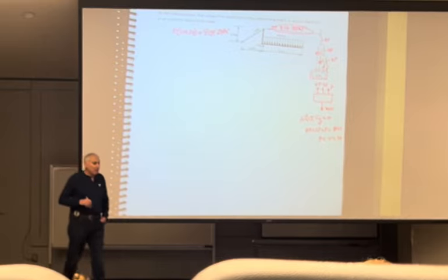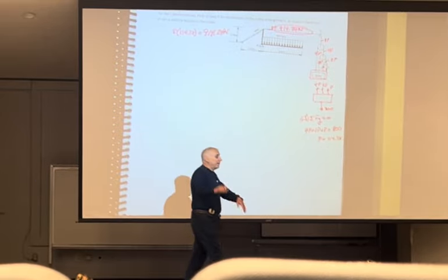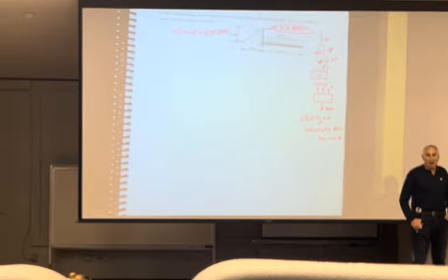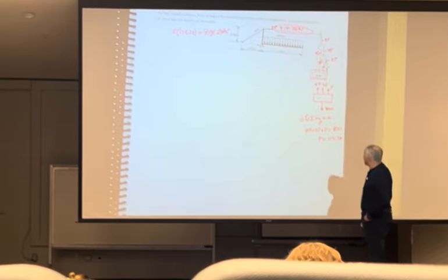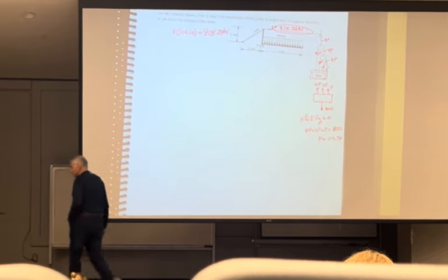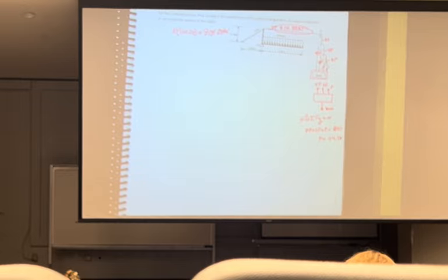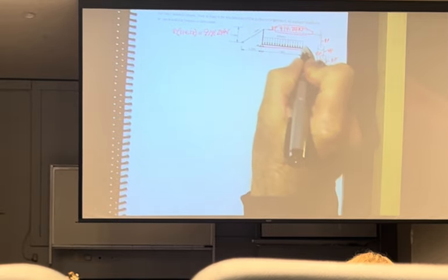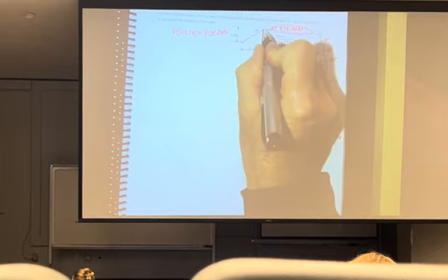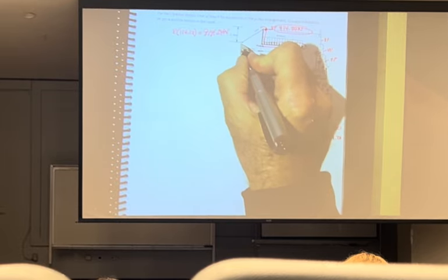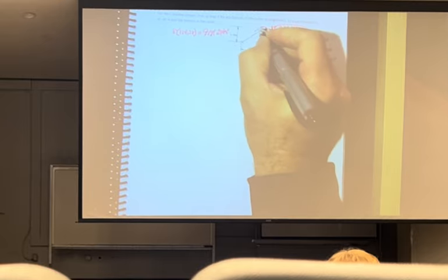That's what that's telling me. So as far as I'm concerned, you can throw away the pulley system. I don't care anymore about it. I got what I needed, which was the 914.24 going to the L bracket. Now I'm going to come in and say, let's do this. Cut through here, cut through there, cut through this cable. And then rather than go through here, that would give me 2 more unknowns, 4 unknowns. The hell with it, I'm going to cut through the cable and back.